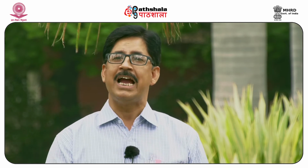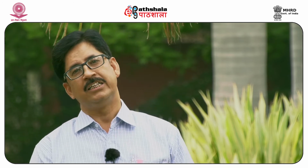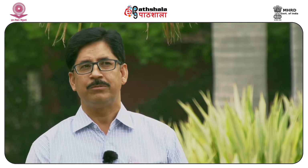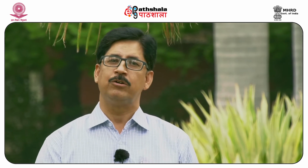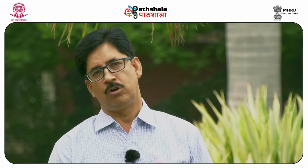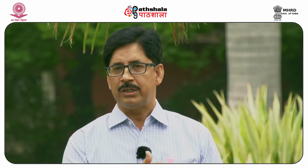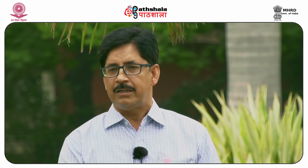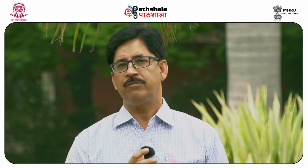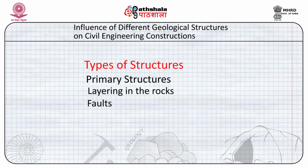In fact, some dams have failed because their foundation was laid on the unconformity surface. The residual conglomerates, which seem to be very strong and robust, failed once water seeped into them, and the whole dam foundation failed. So, these structures play a very important role. If you see their importance, first and foremost come the joints, followed by shear zones and contacts of the rocks, then primary structures, that is layering in the rocks, and finally fault and fold.